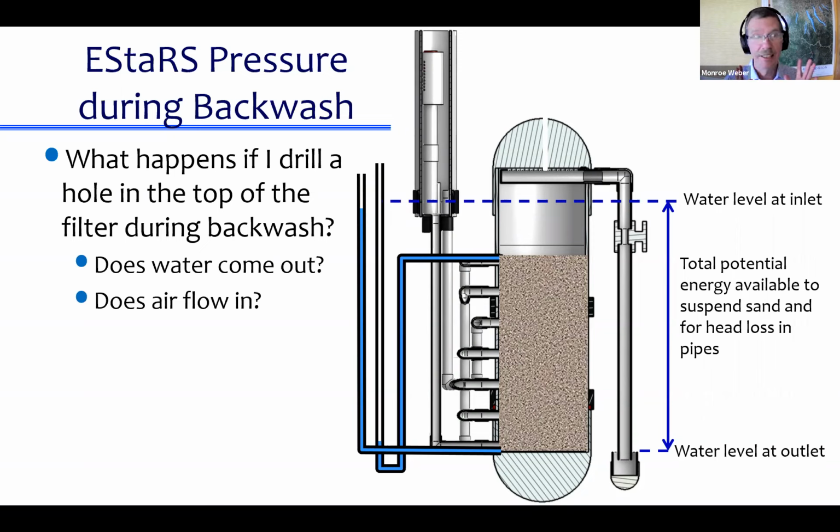it's much easier. When it's operating in filtration mode, it's connected to an outlet tank that's at this kind of level. And when it's in backwash mode, its outlet is way down here. And so simply by opening up this backwash valve, we switch it so that it can access that new low water level, and the pressure like instantaneously drops. And we don't have to dump any extra water. We don't have that big chunk of water above the sand that we just waste.